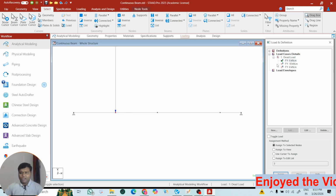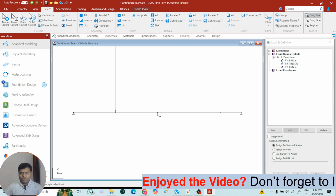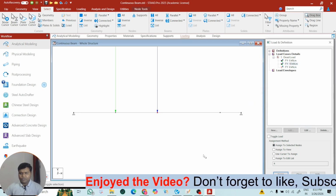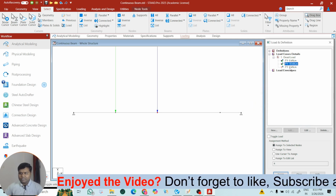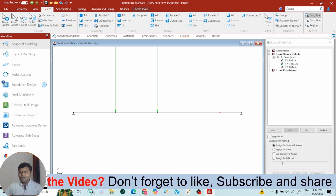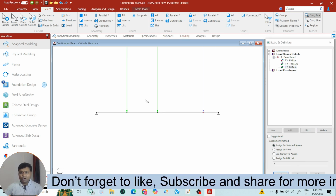Then the second load at the second node. First select load, then select node, and then assign to selected node, assign it. Now select the third load, then select the third node, and then assign to selected node, assign it. See, all loads we have added.